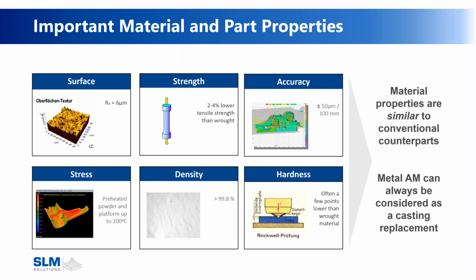Part accuracy. So it is a near net shape, 50 to 100 micron accuracy across the course of an 11-inch plate. So over the course of 280 millimeters, holding 50 to 100 microns, you're not going to be printing threads and having them be perfectly located, but you'll definitely be able to print guidance holes and post-machine perfectly located threads very, very, very accurately.